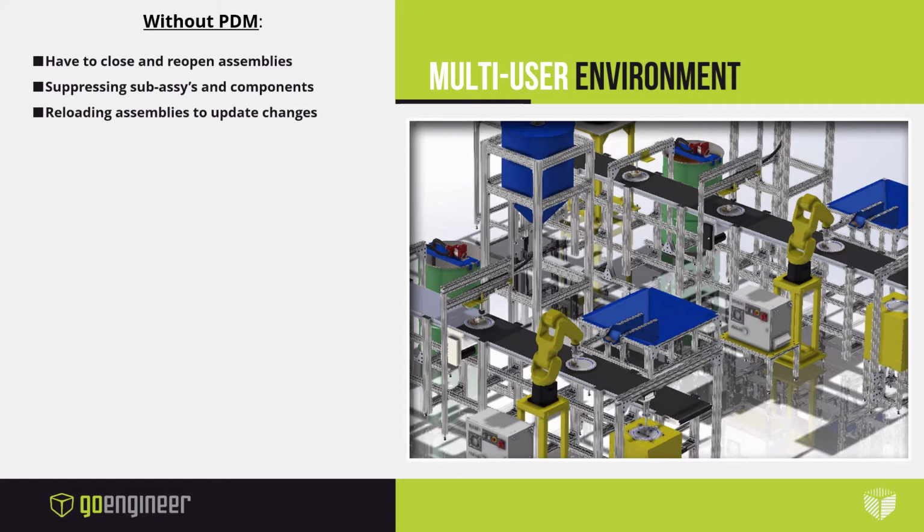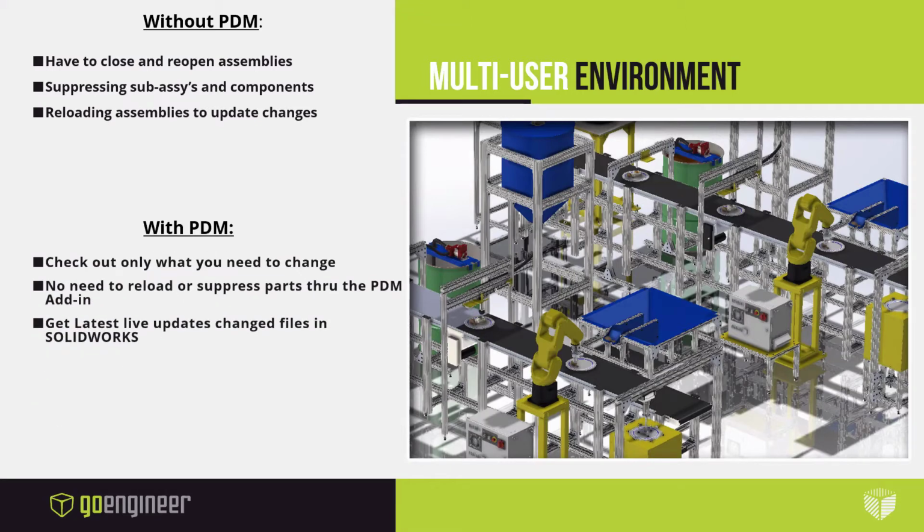How does PDM help with this multi-user environment, as far as being able to juggle these parts around, especially with multiple people working on it? Yeah, absolutely. If I had to say one thing PDM was really designed for, it was the multi-user environment. The problems that you just described come from an inherent nature of Windows, which is that once the file's open in RAM, it's in use by Windows, and therefore it's going to be read-only to everybody else. PDM handles that entirely differently.